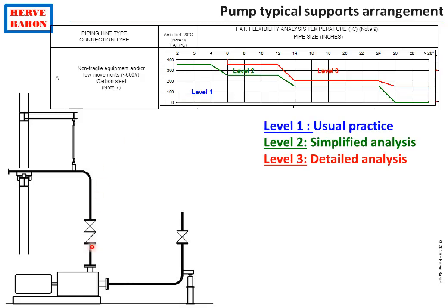For instance, fragile equipment such as rotating equipment makes a line more likely to be a critical line. So charts like this one identify which lines are level 3 lines to be calculated by detailed calculation, level 2 lines, or level 1 lines.